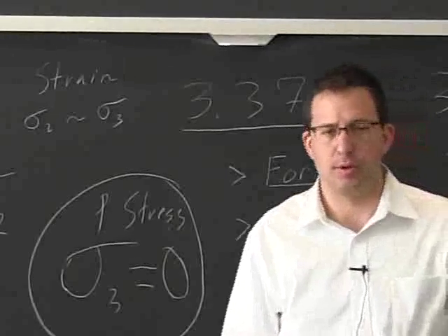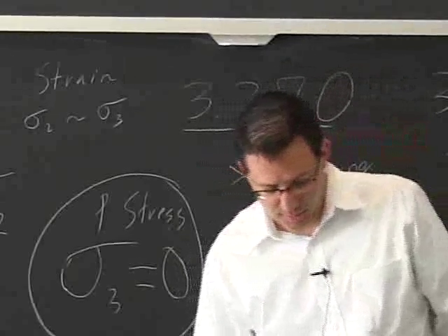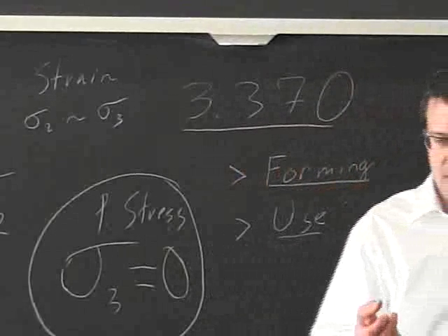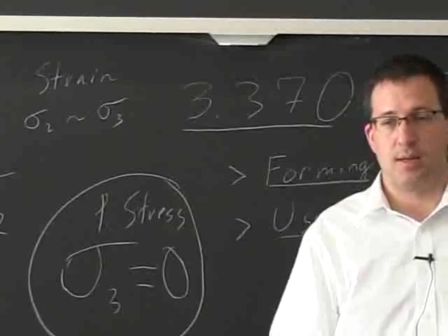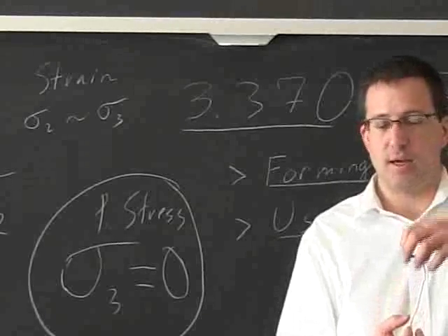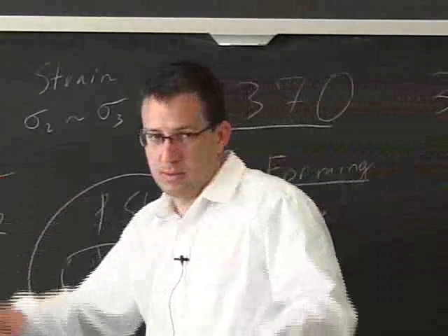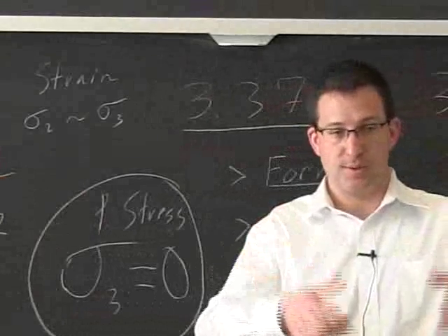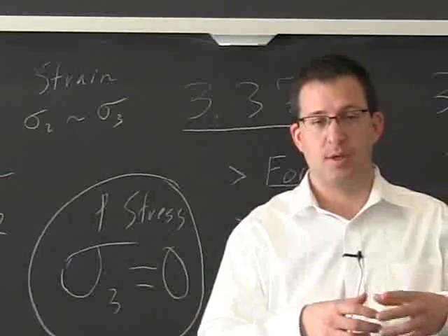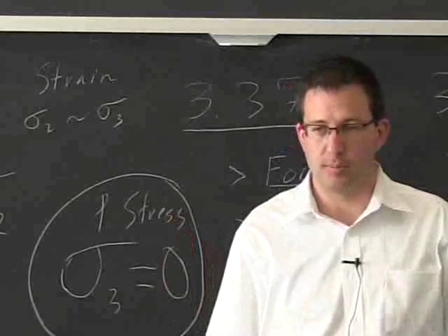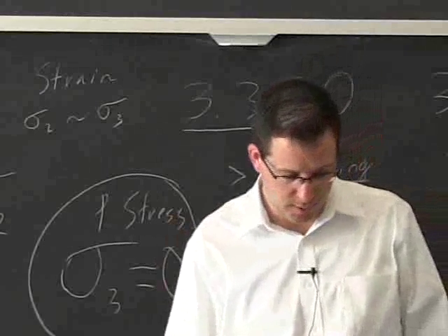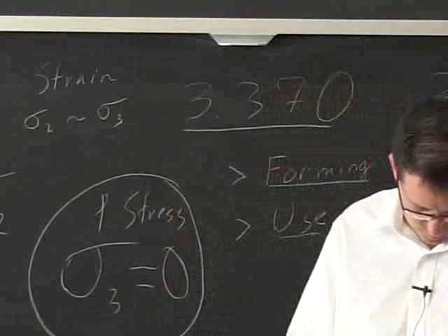And we looked at some of those. If you remember the plastic sample, it could be like a micrometer size, but they're there. And when the stress is high enough and you have that tension, you really grow little voids around those impurities, and that's how eventually it snaps. And you can form a cone and cup shape, like on a tensile test.